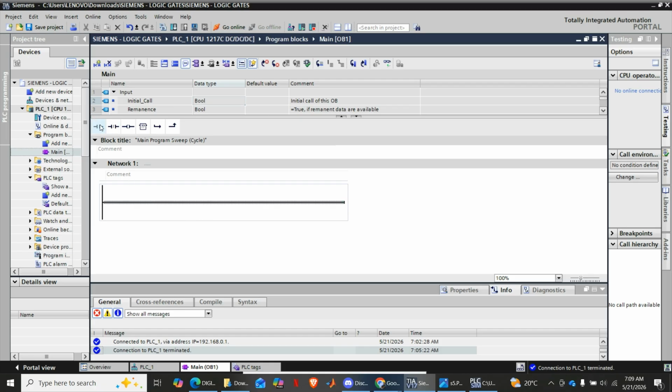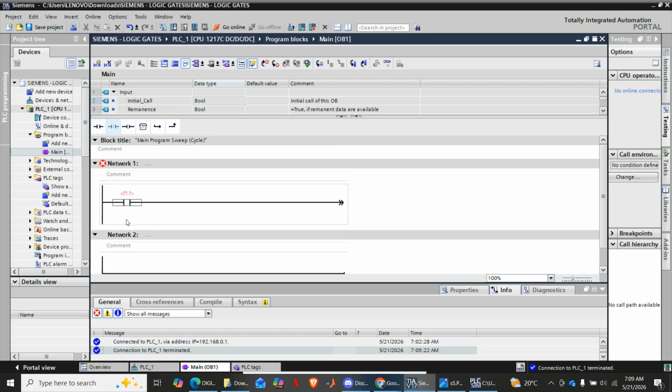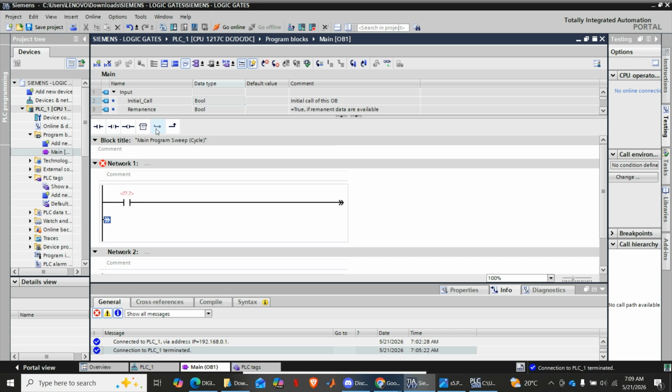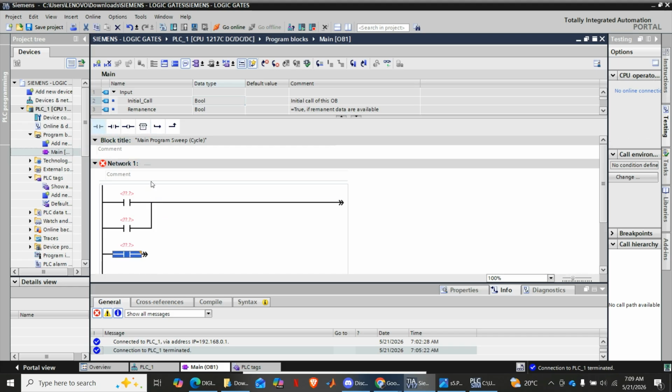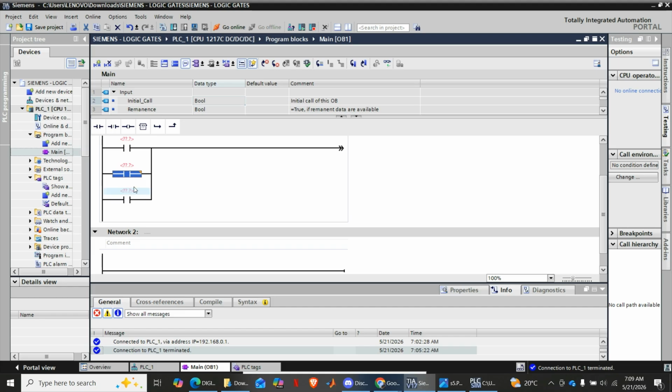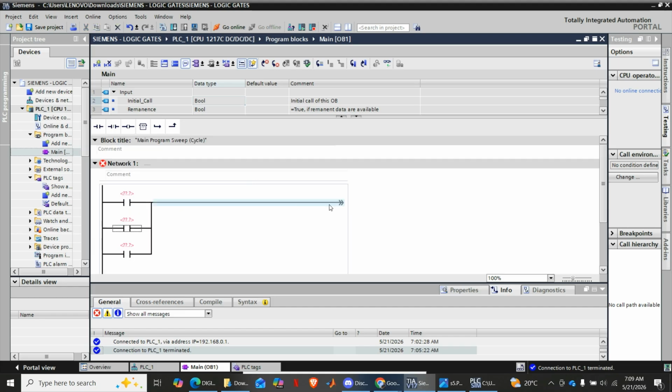So here first we have the overheat detector or temperature sensor, and then parallel to it we have, we close it, the gas leak detector, and then parallel to it, we close it, we have unauthorized access. And now where do we get a set reset block, the SR block?